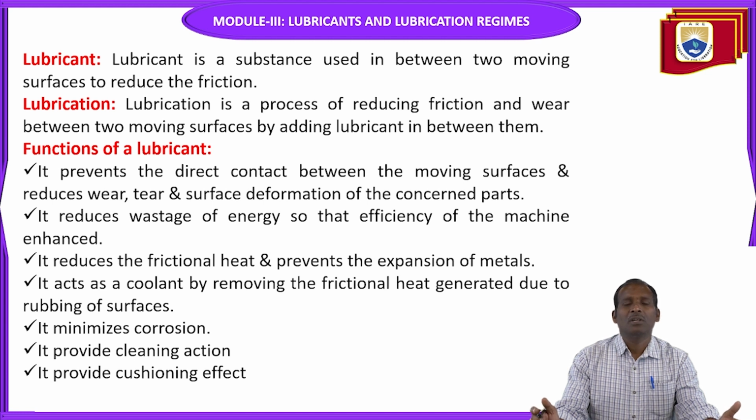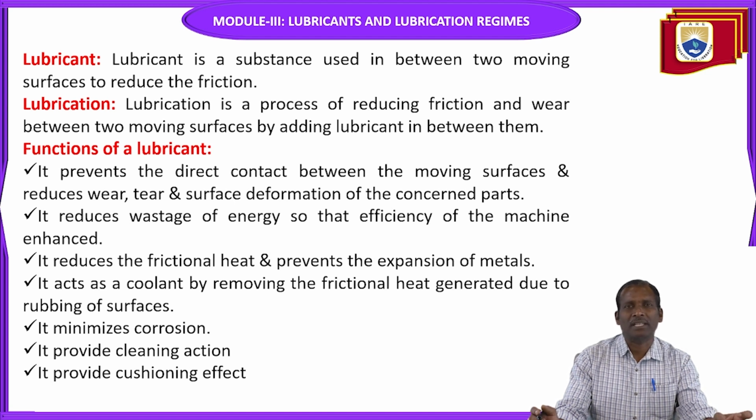Whenever two surfaces are in a mating position, there must be friction and heat generation. The heat must be dispersed to the surrounding area. The lubricant acts as a coolant, removing the frictional heat from the main source and transferring it to the surroundings. Due to this, you can maintain a safe temperature inside the component or rubbing surfaces.